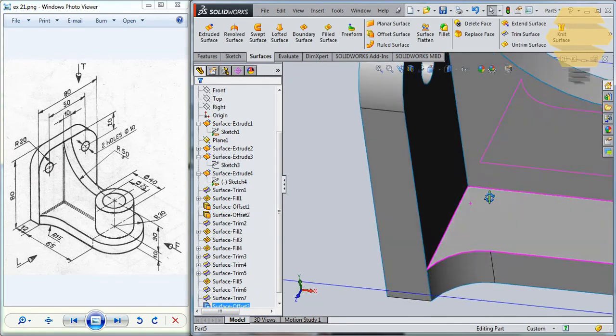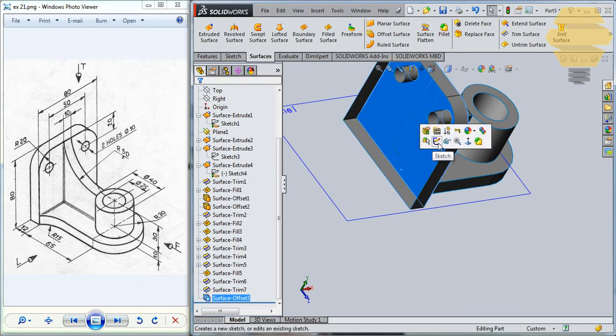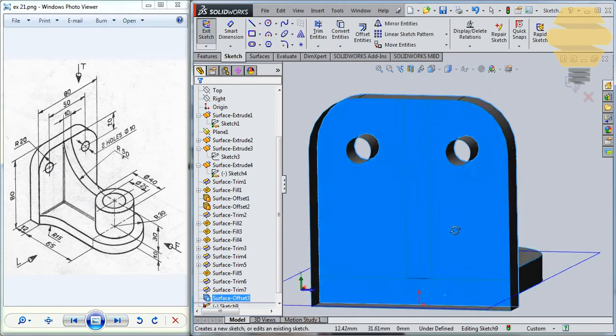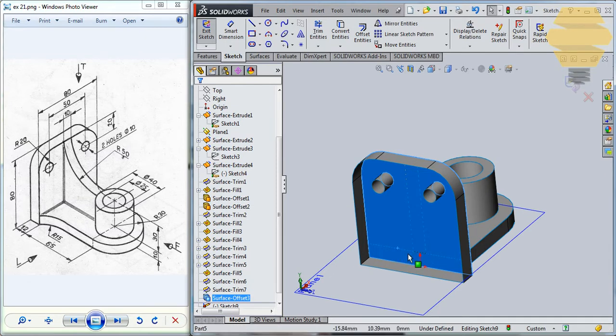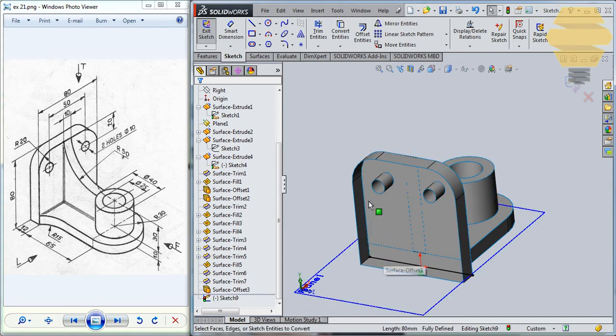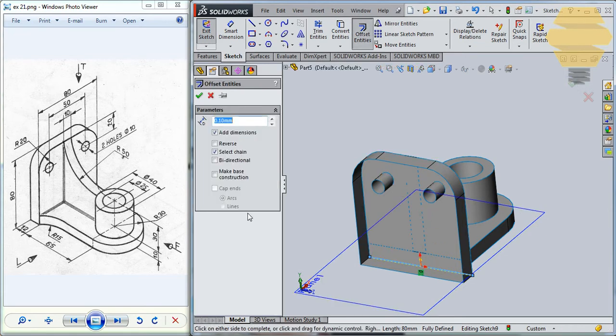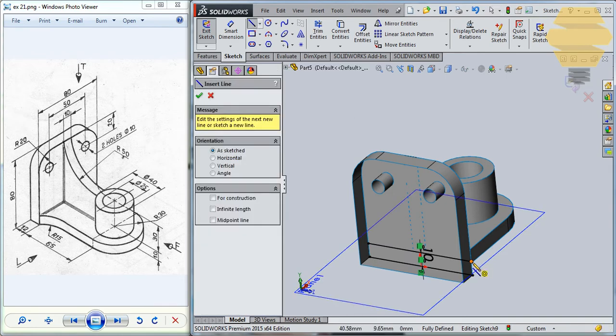And that's kind of filled, but what you gotta do is remove this portion, so you can go for sketch, and basically what you're gonna do is convert entities and select that line. Maybe you can just go for offset and give an offset of how much. That could be 10 there, and the reverse direction 10, and you can just close that loop there by using lines.